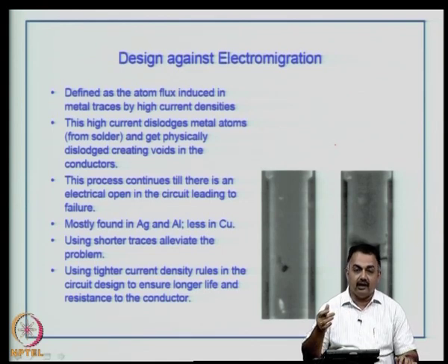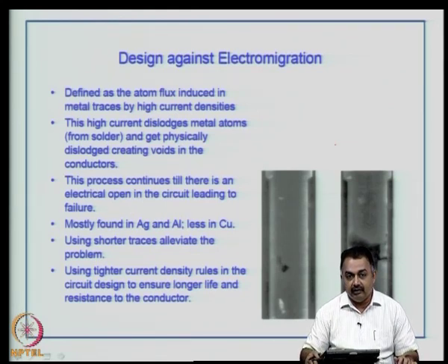and the different current densities that you are using and the kind of moisture levels, the kind of external debris and process debris if they are there, can make a situation where you can have disturbances in the copper in terms of voids or creating what is known as some kind of whiskers in tracks, which can lead to a short due to electromigration, but this is a slow process.